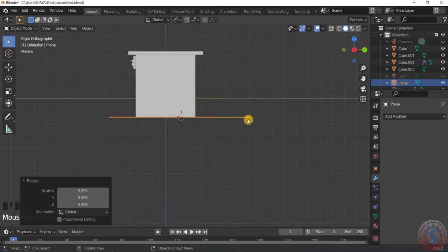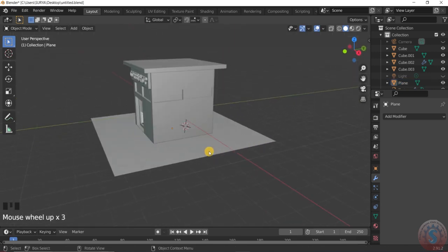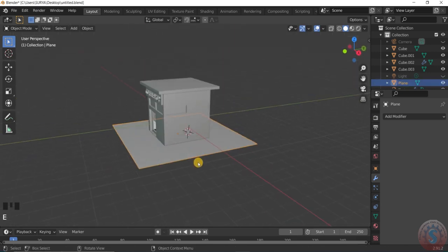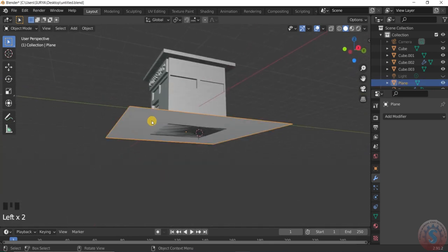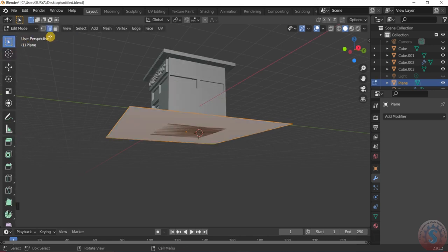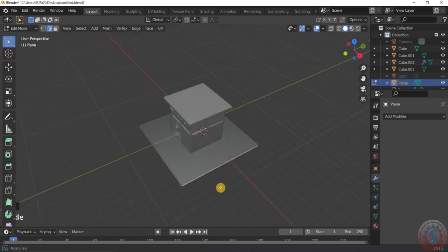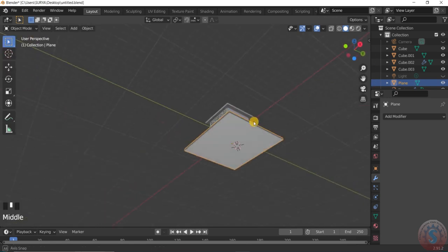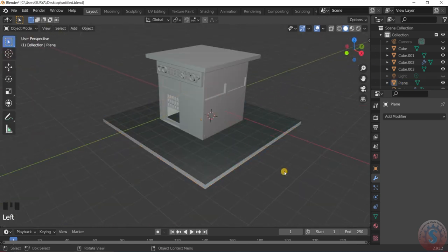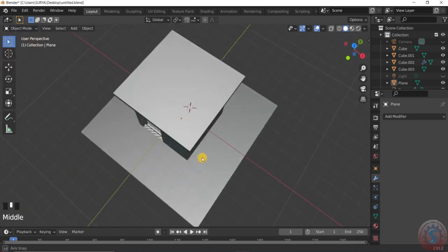On the 3, use the G and the X key, in the directions to the center, and extrude this. Go to the edit mode and give the extrude option for somewhat of a thickness, and go into the object mode.